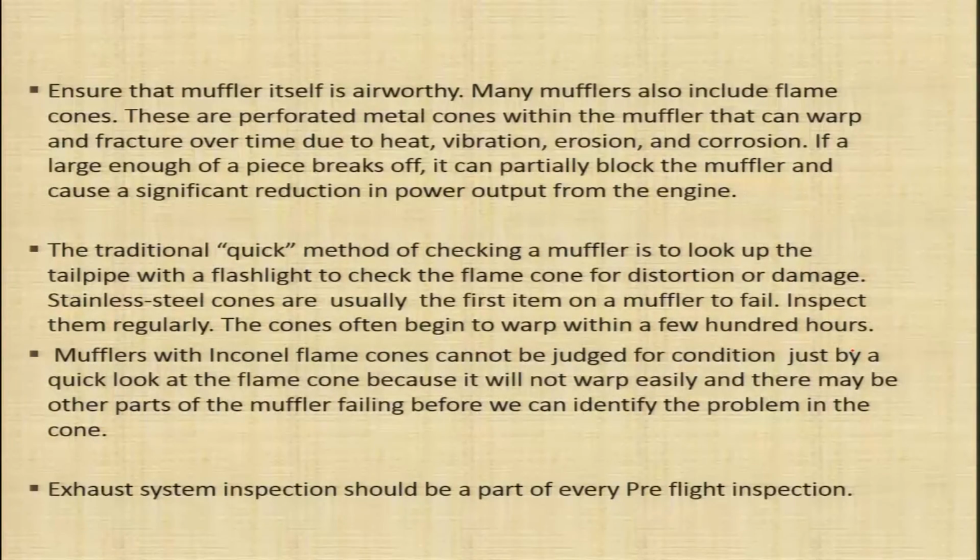Many mufflers also include flame cones. These are perforated metal cones within the muffler that can warp and fracture over time due to heat, vibration, erosion and corrosion. So we need to ensure that the mufflers themselves are airworthy. If a large enough piece breaks off, it can partially block the muffler and cause a significant reduction in power output